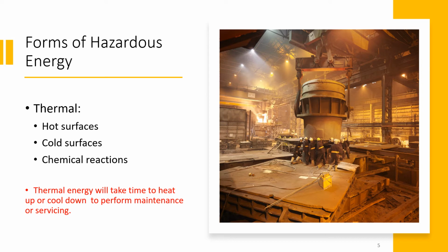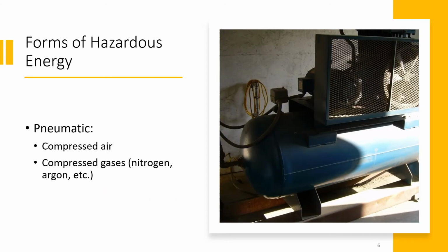One thing to remember with thermal energy is that obviously it's going to take time for something to heat up or to cool down, depending on what the thermal energy is, so that you can do that maintenance and servicing and figure out what's wrong. That is something that will have to be factored in when you go to do the lockout tagout. If you estimate it's going to take an hour for this thing to cool down, that's something that you have to factor in, so that you have a realistic expectation when working with others about how long a job will take. We'll go on to the next one here.